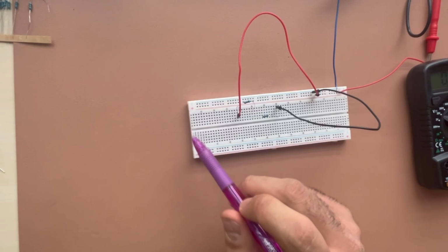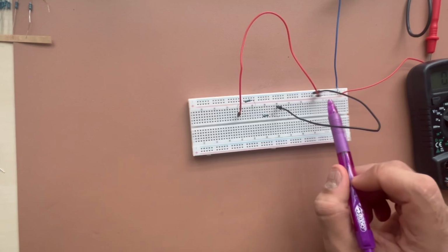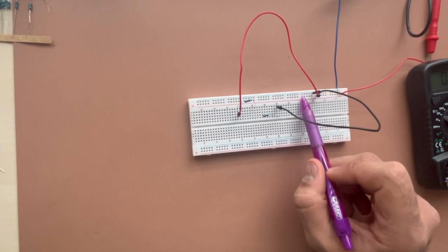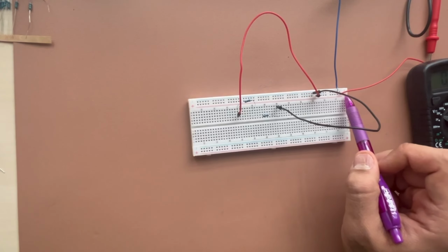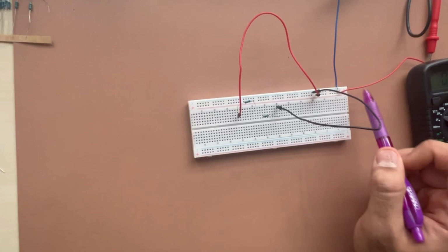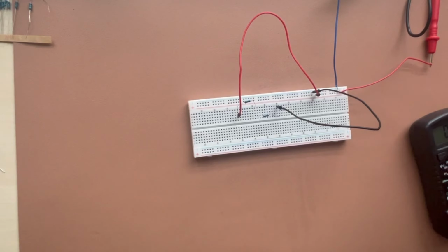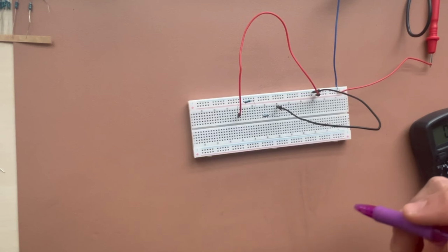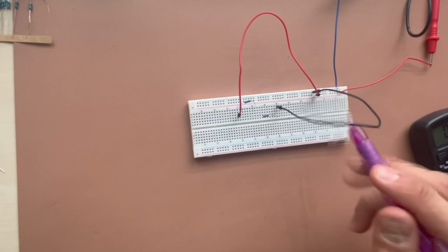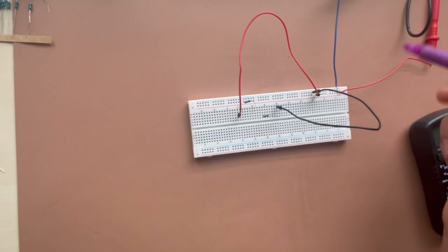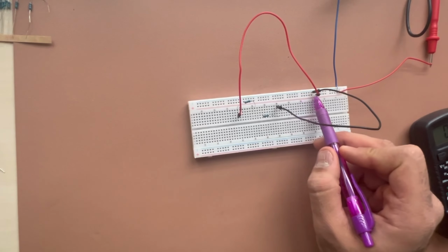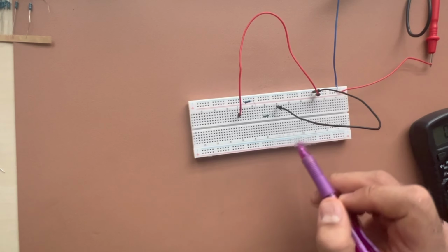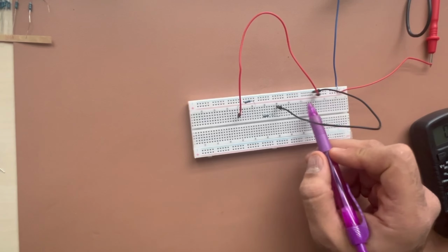On the other hand, when we're talking about the power rail, on the top side we have two rows. The very first row is considered positive. As you can see, it is connected through the red wire to my power source. You don't see it right now probably, but it is connected. Then I have this blue one, which is connected to the negative side of the power source itself. It means that all of these spots in the vertical side are connected to each other, and in the horizontal side are connected to each other.